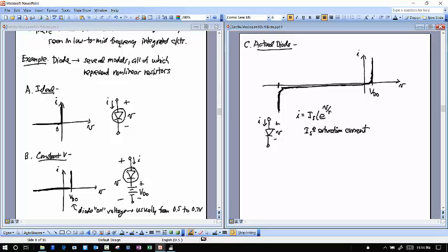So it's usually V over some N times V sub T. V sub T is a thermal voltage. So that's at room temperature around 25 millivolts. And that's really Boltzmann's constant times temperature divided by the unit charge. And I've already called it what people generally call it, which is the thermal voltage.